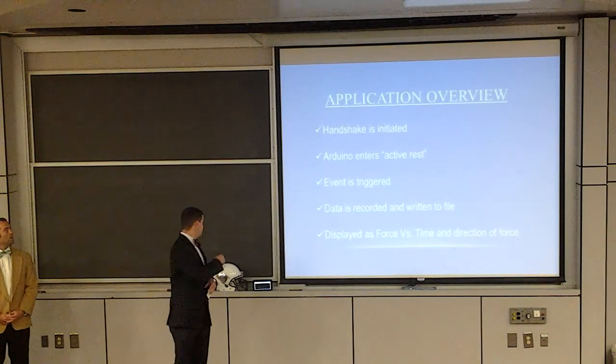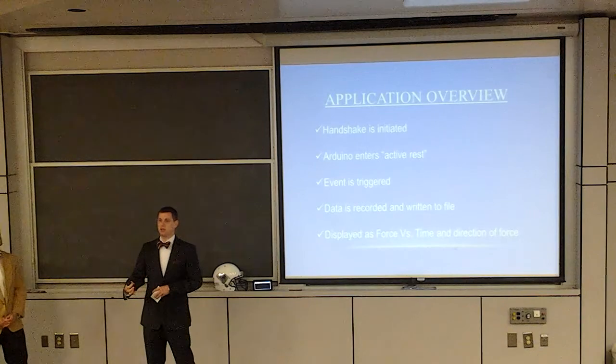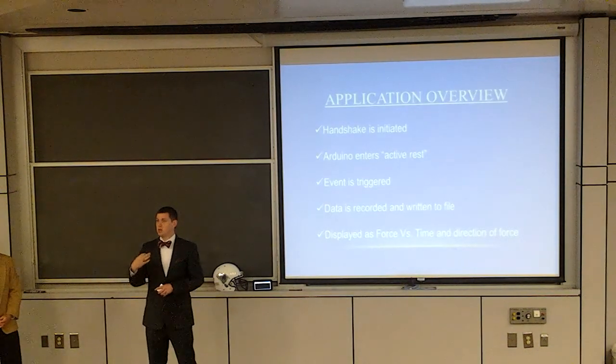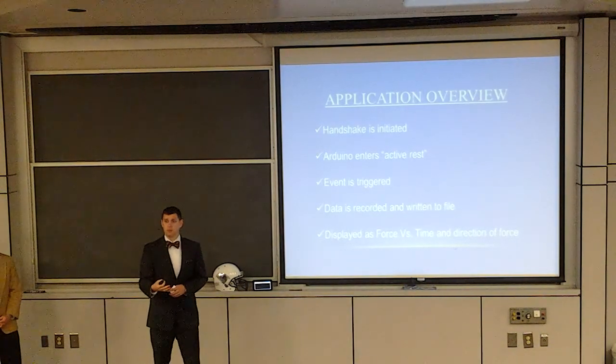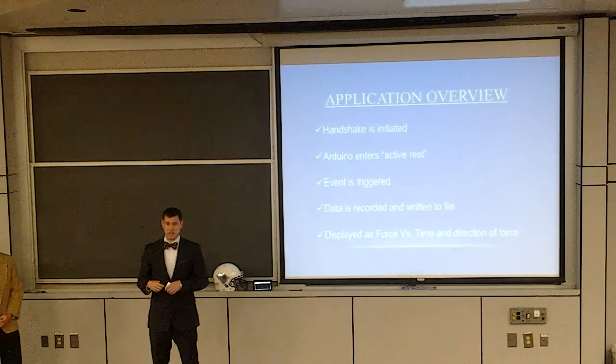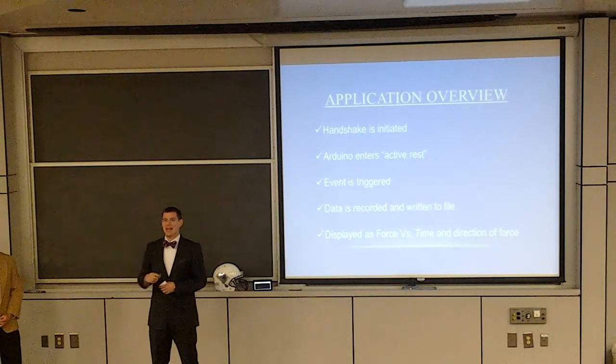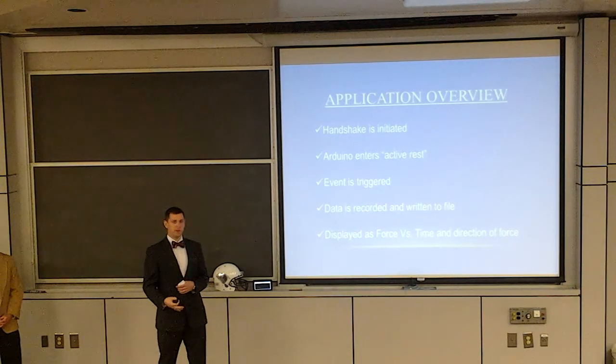What actually happens when we set up our tablet, we create a handshake. The tablet says, I'm ready to talk to you for a little while. The Bluetooth transmitter says, all right, we're good, and then a secure channel is actually reached. The Arduino then enters an active rest stage. The active rest stage is a way for us to conserve battery power.